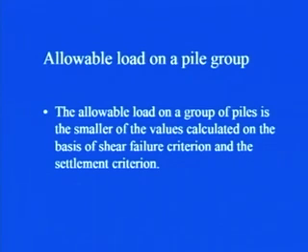Then the allowable load on the group of piles is the smaller of the values calculated on the basis of shear failure criteria and settlement criteria. The group has to be stable or safe against shear failure, as well as the settlement should be less than the permissible settlement.